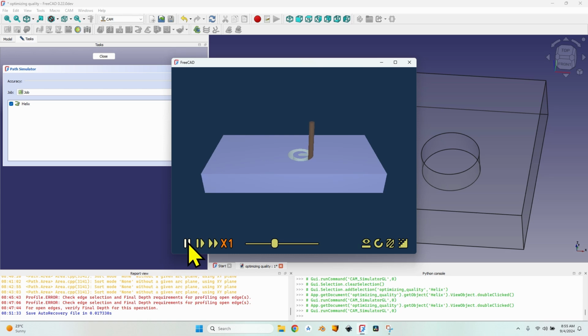So whenever you are having trouble with the final dimension of certain holes, remember the tool bit deflection. The smaller the tool bit, the larger the deflection will be. Most probably the hole won't have the correct diameter. If you want to have the correct diameter, always start from the outside, even though there is a risk for the little bit that remains in the center to be thrown away and damage the cutter head. You simply cannot get the correct dimension using start from the inside.